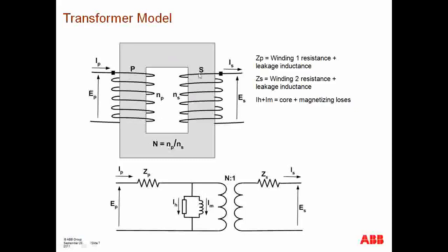So basically you have a core. In the case of power transformers, you have a core, which is usually made out of a soft steel, providing a path of low reluctance to the flux. You have one winding that's connected to a particular voltage level, and then you have another winding which is connected to another voltage level. You could have 3 winding transformers, in which case you would have 3 windings connected one on top of the other, and we will see a picture of that in the next slide. This is just a basic representation of a single-phase transformer where you essentially have what's known as an ampere turn balance, where the primary current times the primary winding turns must equal your secondary current times the turns of the secondary winding.